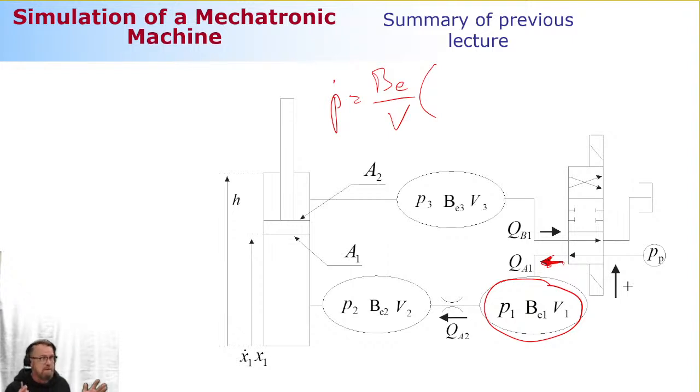And let me emphasize, it's extremely important that you do these drawings, because you might think that you have such a big brain that you can memorize the positive direction. It's not going to work out. You make one simple mistake in your flow directions, and your hydraulics always go crazy. It makes no sense whatsoever, and hour in, hour out, day in, day out, week in, week out, you still can't figure out what is wrong in your hydraulic circuit. So please be as careful as you can.